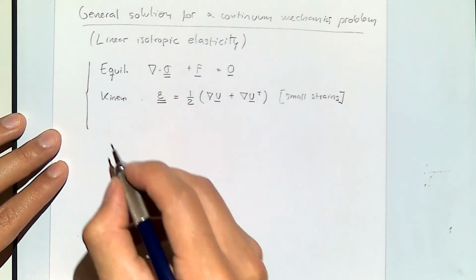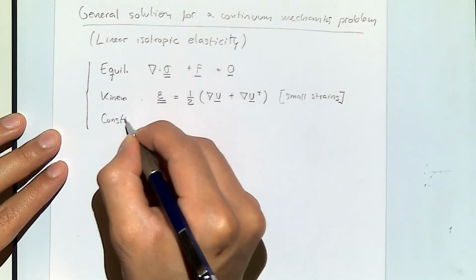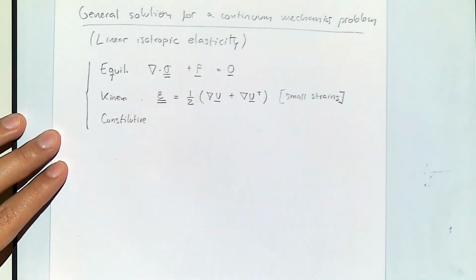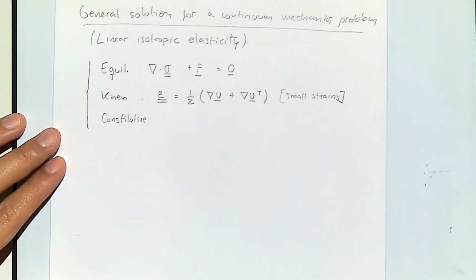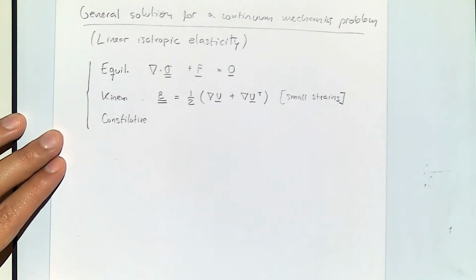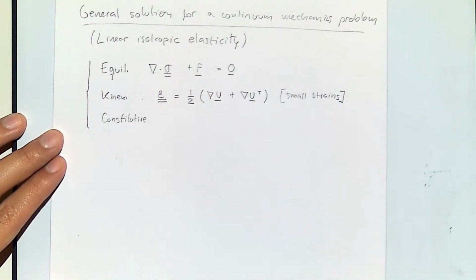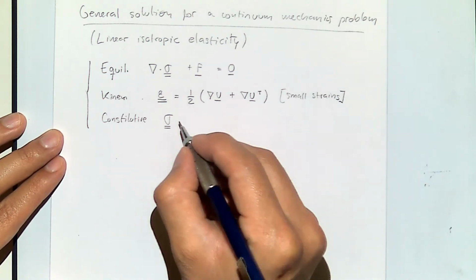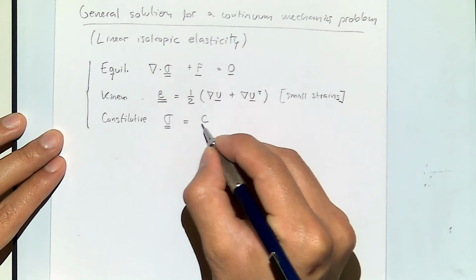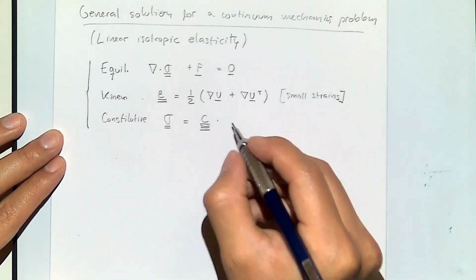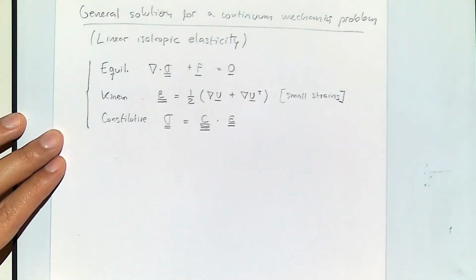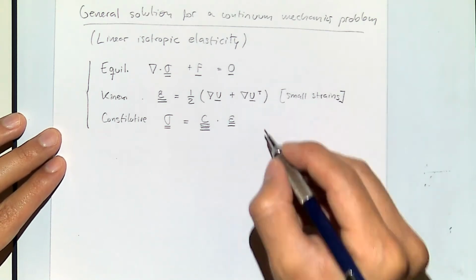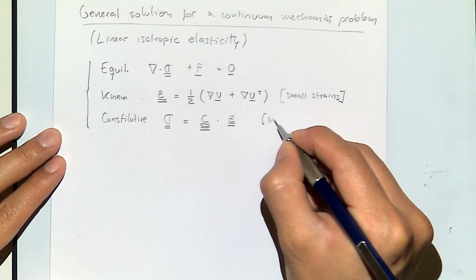And the last one is the constitutive, and we have spent quite a bit of time with the constitutive. We saw first isotropic elasticity, and then we just finished seeing anisotropic elasticity, and later we'll add poroelasticity to it. But it's all part of the constitutive equations. And constitutive equations allow us to link stresses and strains through, in this case, the stiffness matrix. In this case, this is linear elasticity.